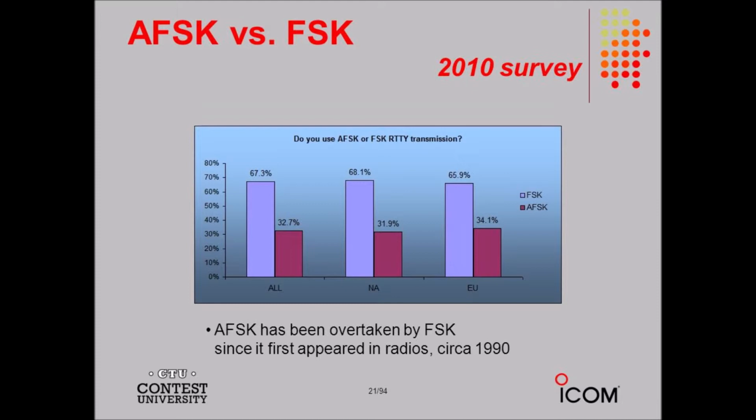An AF voice signal has frequencies mostly in the range between 300 Hz and 3 kHz. We can modulate some characteristic of an RF carrier with an AF voice waveform, thereby transmitting the voice information over the airwaves. Figure 25.2 shows a simple circuit for obtaining amplitude modulation, AM.